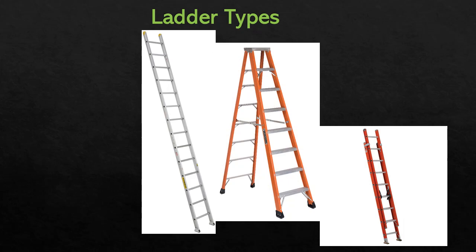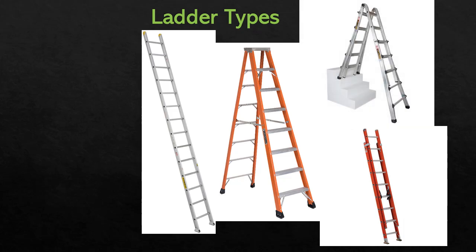This is the A-frame ladder that you see a lot, particularly indoors and in residential settings, places where you don't necessarily need a lot of elevation gain to do your job. There are different types of articulating ladders that look like this one that can be set up in all sorts of scenarios. In this case, we have one that's set up for changing a light that's over a stairwell, and they're designed for this type of operation.